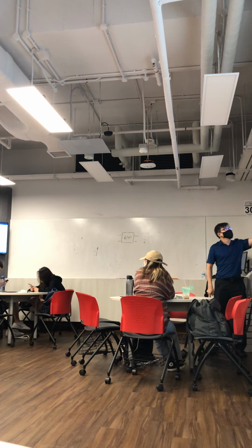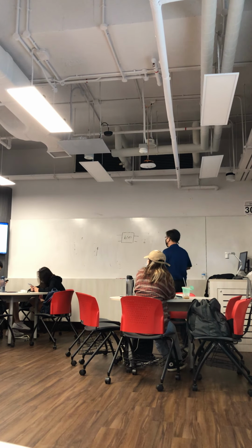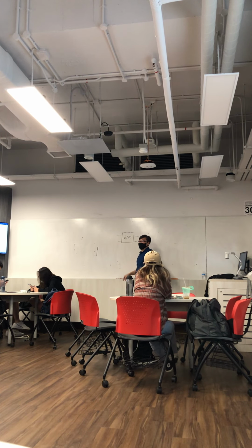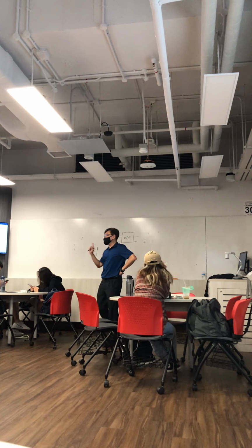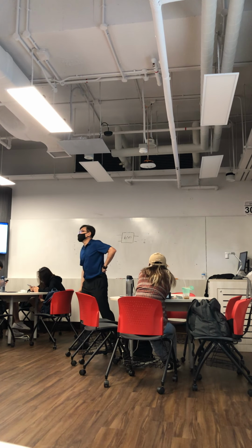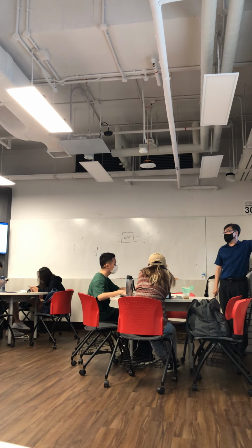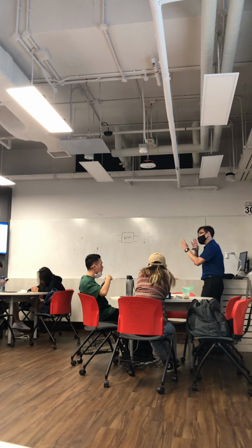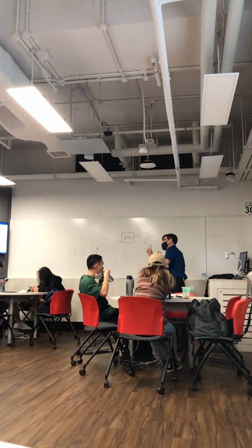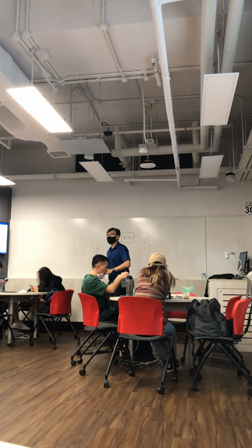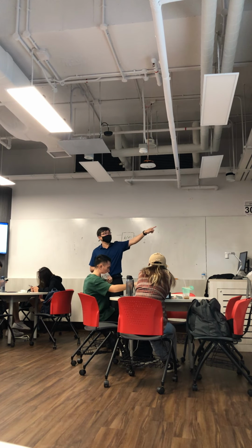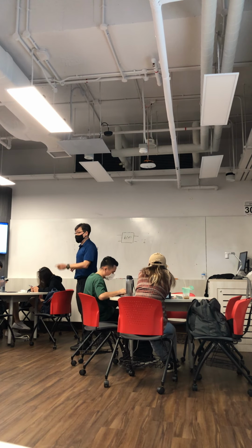Okay? So once you know this h(t) of this system, now you apply any signal and I can tell you what the output is. Because for any input x(t) you apply, you basically do a convolution: you take the input, multiply, and shift it across time. You get the response, and that response is your output from an unknown input.